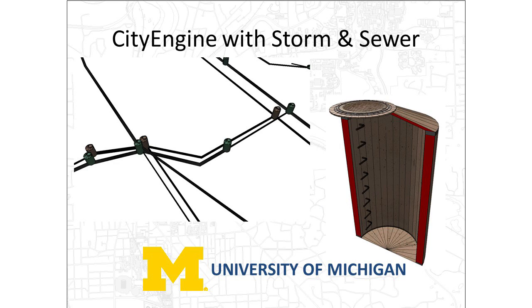Now, one thing you don't want to do, this is an excellent model, but when you're going to try to do a whole campus and you've got 3,500 of these things, don't bother going through the modeling of the rungs inside the manhole. It's just going to take forever to generate for you. So when you're looking at other models, try to keep them as simple as possible. It's nice that the manholes are off center on these, because that is reality for the way the data is, because you do have to have ladder access. Typically you don't have the manhole in the center because you've got to get to the ladder to safely go down, but you don't want to show it.